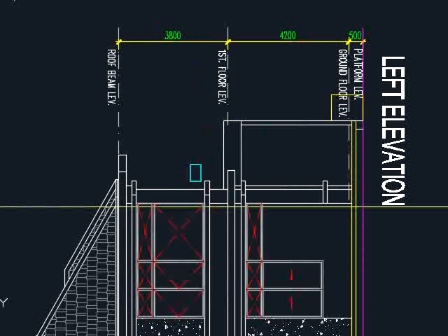You have to find a mechanism to have this supported. And remember, you have another fin here. Most likely you're going to have your concrete beam to the soffit of the fin here, and provide reinforcement bar so that the fin here can be attached together to the perimeter beam. Same goes to this design. Most likely the soffit of the beam will reach up to this level.